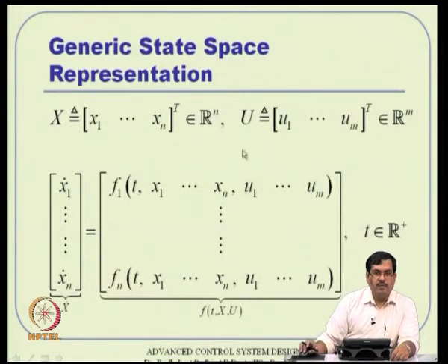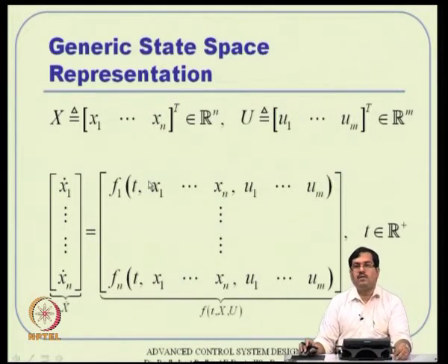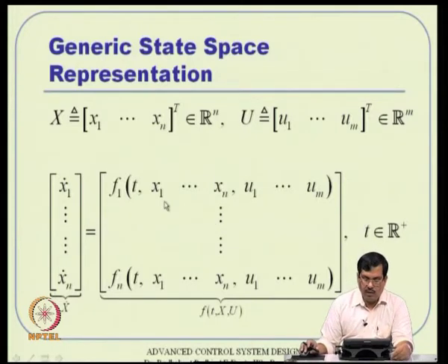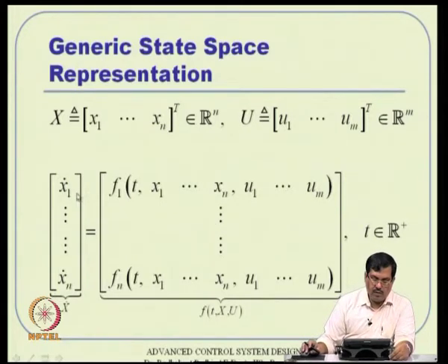Okay. Now, if you define it like that, the state space representation of the system dynamics of a system in general can be represented something like this. X1 dot is some function of time t. Remember, t is an independent variable, it belongs to R plus only, it is a positive quantity by default again. There is no restriction as such, but we will take time as a positive quantity, and in some applications we require backward integration, we require some negative information as well. Okay. But by default we will take it as a positive number. Okay. So, we are assuming these system dynamics are always propagated forward in time basically. Okay.